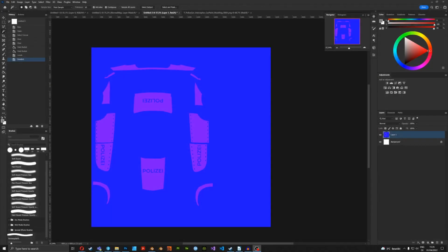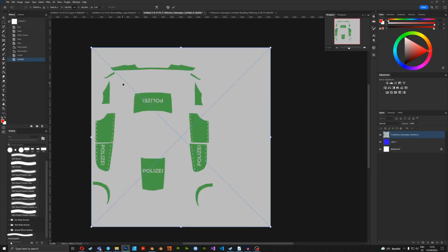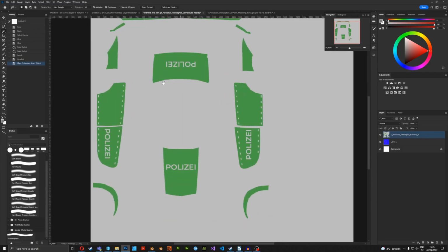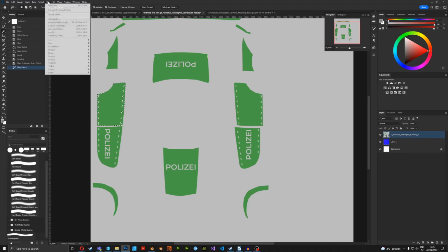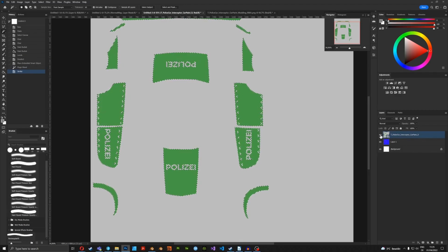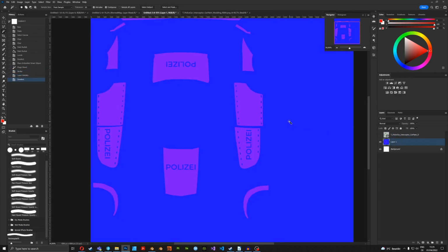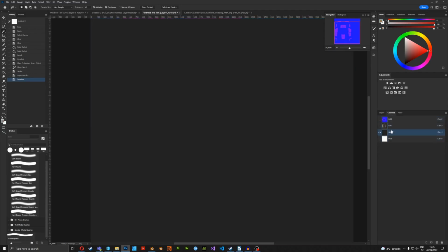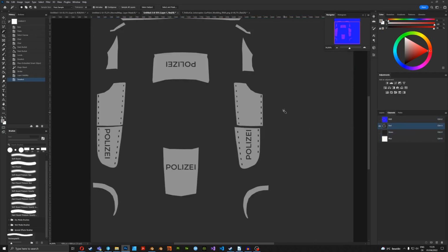The third step was to create an RMA texture, and that was done quite simply. I just added in my base color texture and used masking again to select some parts which I wanted to have a certain roughness. So I always started by creating the roughness map, and to create the roughness map, which you can see in this red channel, I just selected the gray part, made it a bit darker because it should look very smooth, and after that I marked the other part and made it a bit lighter to make it a bit more rough.